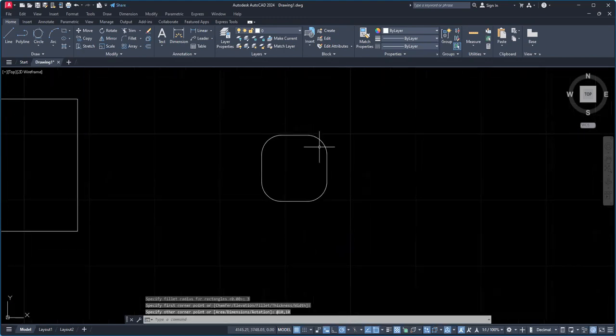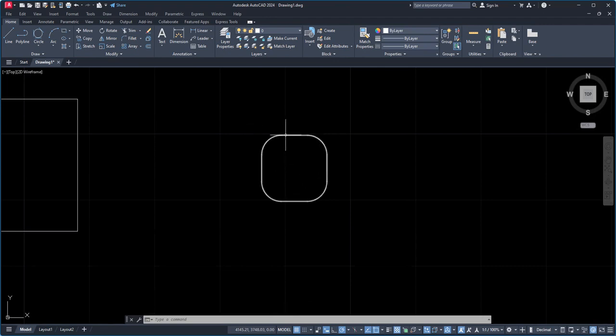So why should I give 10 and 10? Because here the fillet amount is 3 and here also the fillet amount is 3. 3 plus 3 is 6. Okay. The rectangle or the square dimension should be more than 6 so that you get a rectangle. Otherwise, you don't get a rectangle.